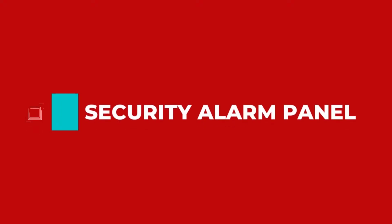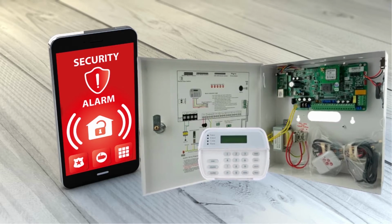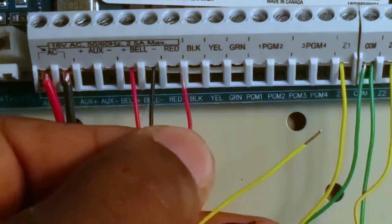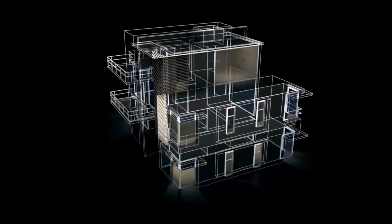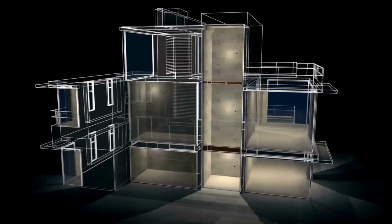Security alarm panel. An alarm control panel is a central hub of a security setup. All these devices used in the system are connected directly to the control panel, which also powers them. When purchasing an alarm panel, you will need to have a general knowledge of the area that needs to be protected and how you plan on dividing the areas into zones.